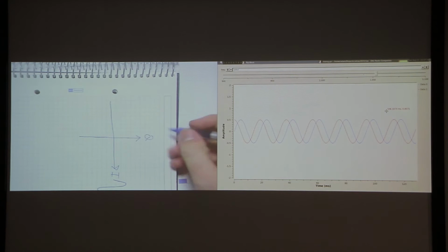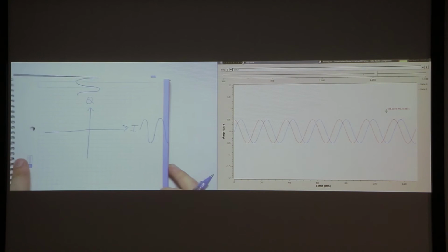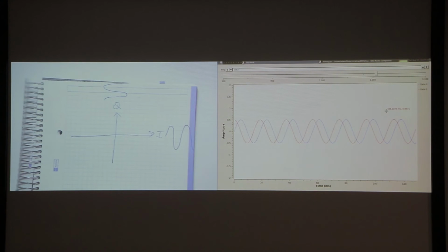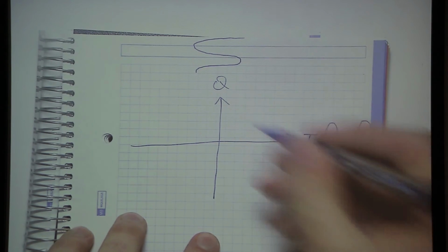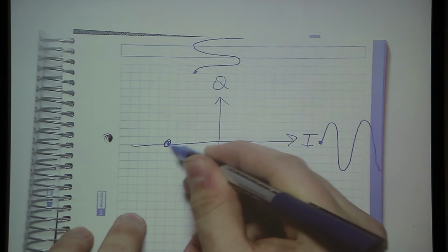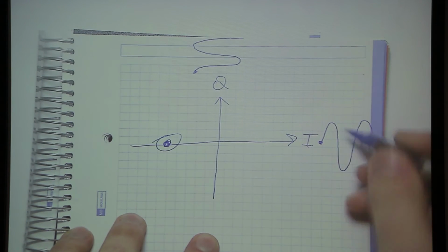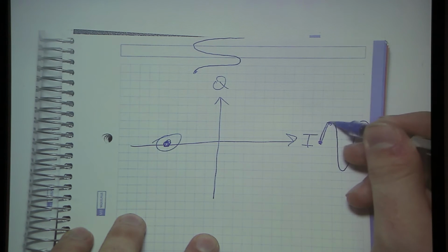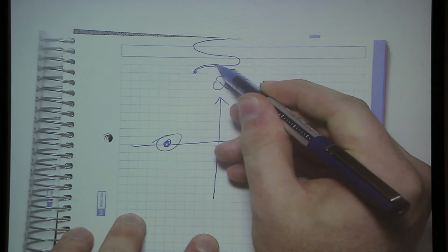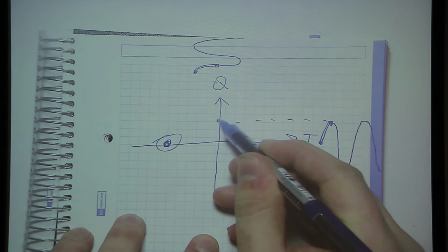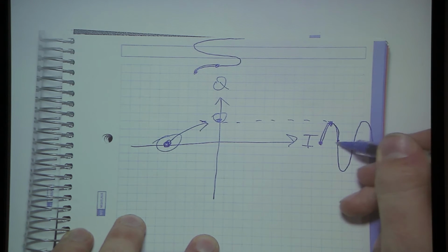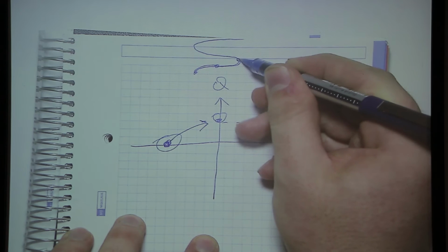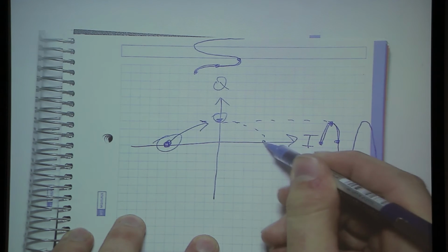And if we rotate and think of a Q line, it's out of phase against time, which means if we were to plot the IQ point, then at the first moment of time, I is at 0, Q is over here, our point is here. A short moment in time later, I has risen up to this value here, and Q has come down to 0 here, and our point is now up here. A little while later, I is back to 0, and Q is at a maximum over here. Our point has moved down to here,